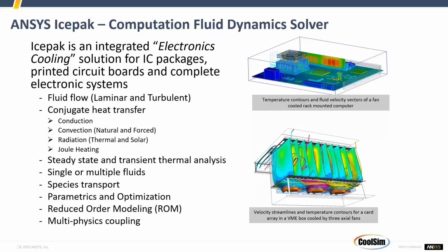So we can do all sorts of conjugate heat transfer analysis, conduction, convection, radiation, and Joule heating, in steady state and transient, and also look at single or multiple species of fluids.